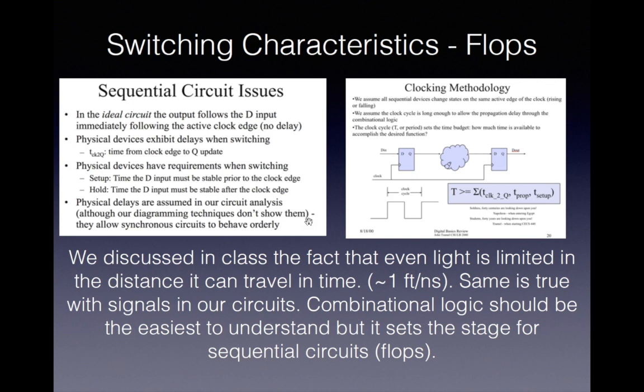So again, when we model or simulate and we look at the waveforms, everything happens instantaneously. So on the active edge of the clock, the flop switches, it looks like the Q switches immediately. You need to keep in mind that in reality, and even in the way they model the Verilog for simulation, there will be a delay from the active edge of the clock until the output of the flop switches.